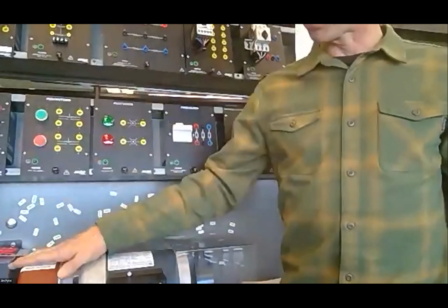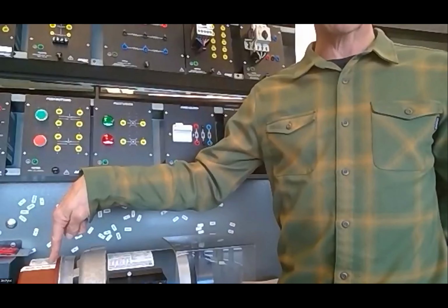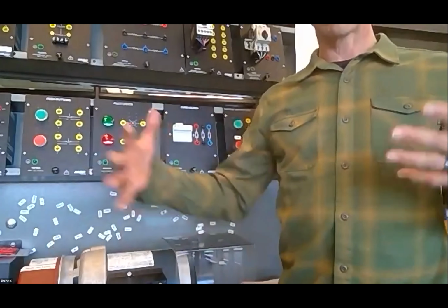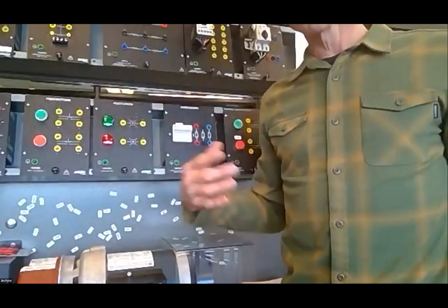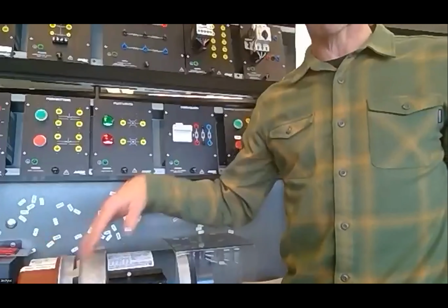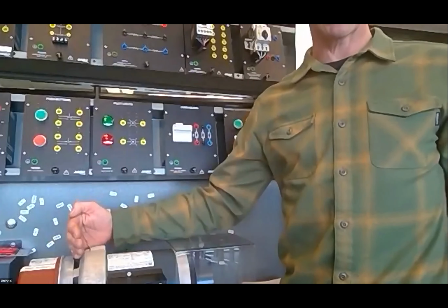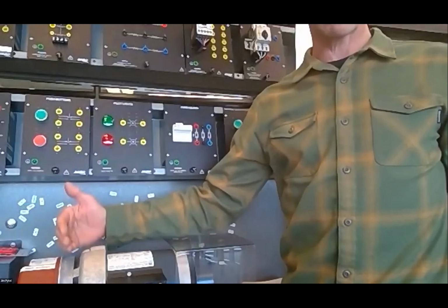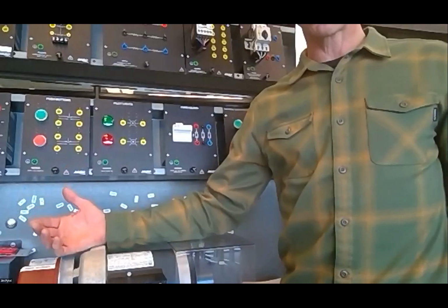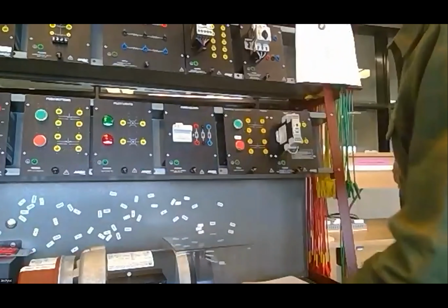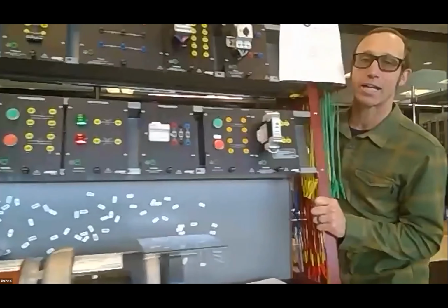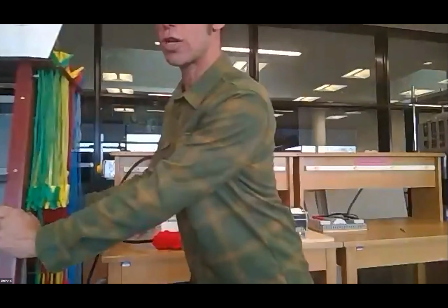motor starter. The other thing I could say about this is that there's a friction brake on here. It is a spring-held, electrically released brake. So it's always a great thing to show them what happens in a locked rotor condition when the brake fails to release. Obviously, the motor goes into an overload. So troubleshooting a scenario with that is a great way to introduce that piece of equipment. You don't necessarily need this piece of equipment, but that's the first time I actually use it.